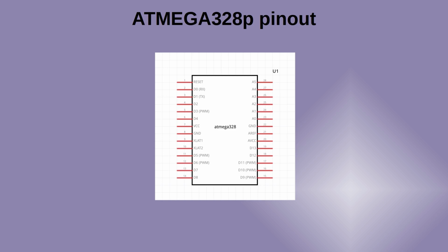Before we move on, I'd like to dispel a possible misunderstanding. Just because I2C uses the pins that are known as analog pins does not mean that I2C is an analog signal. It's a digital signal driven using an open drain. It's just that the internal I2C circuitry is connected to the same pins that are used for 2 of the analog to digital converter inputs. The mode of the pin can be changed through your code on the Arduino.